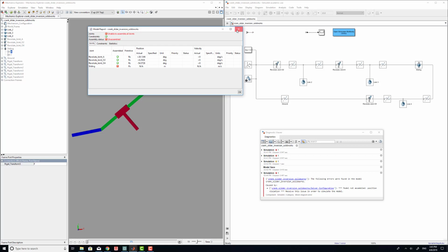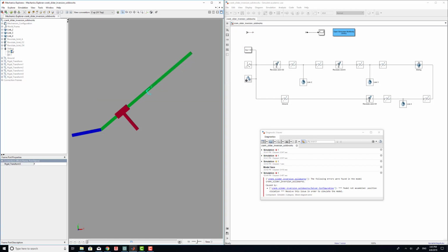So that's why we have to focus on the coordinate system of your sliding joint, and then we can see the base, something like this. Your follower is something like that. So okay, we find the problem. In this case, you can see that the z coordinates are aligned, but the xy coordinates are not, right?